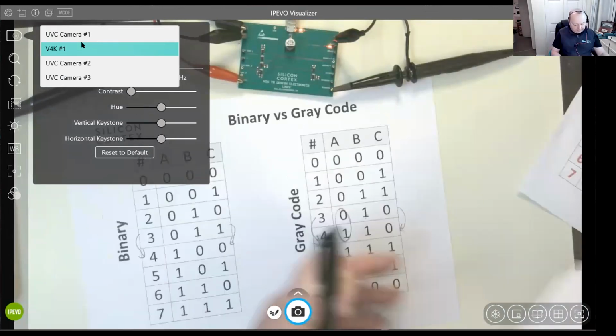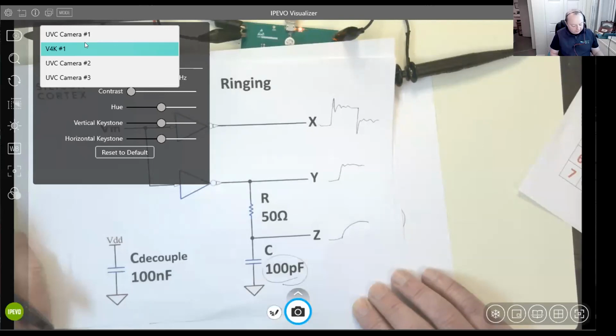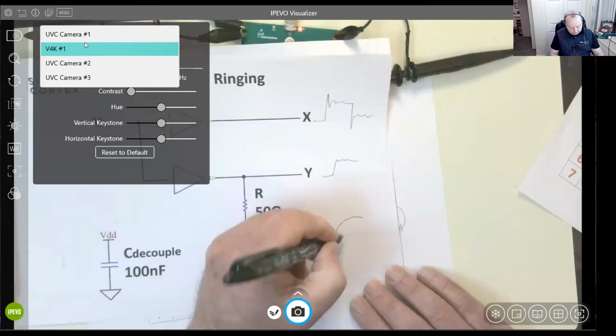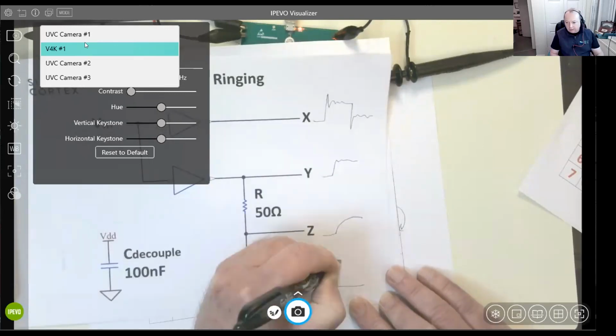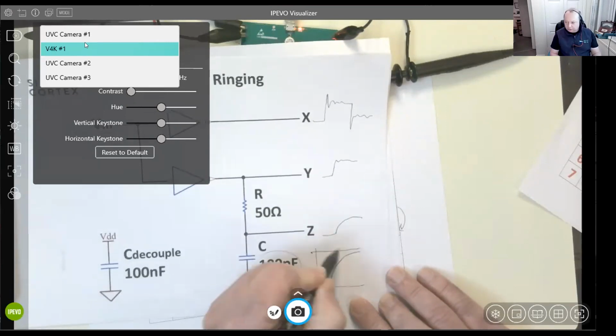So they had such a high value here that it caused the output to start to slope. And of course, if it's too large, you might end up being below the threshold level before you want to go logic 0. So you can overcook it.